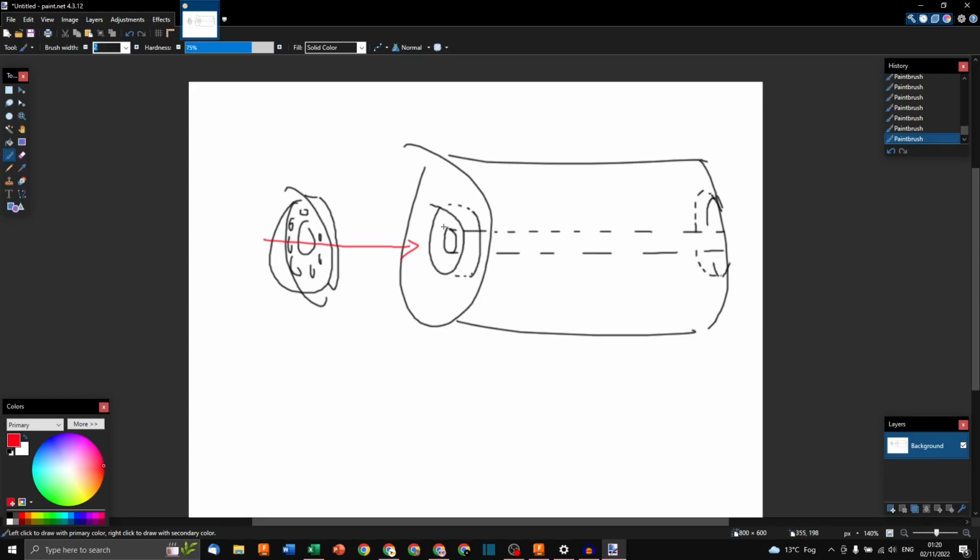The front bearing seat will be a bit smaller in diameter than the rear bearing seats. This makes the assembly easier because you can push the arbor through. So inside of here will be an arbor without tolerance issues. So two bearing seats, a wheel. We'll also be making a tire today on the exterior of the wheel.